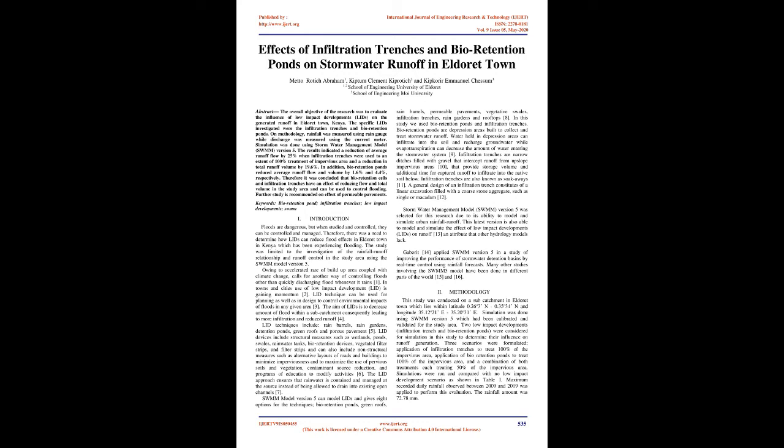1. In towns and cities, use of low-impact development, LID, is gaining momentum too. 2. LID technique can be used for planning as well as in design to control environmental impacts of floods in any given area. 3. The aim of LIDs is to decrease the amount of flood within a subcatchment, consequently leading to more infiltration and reduced runoff.